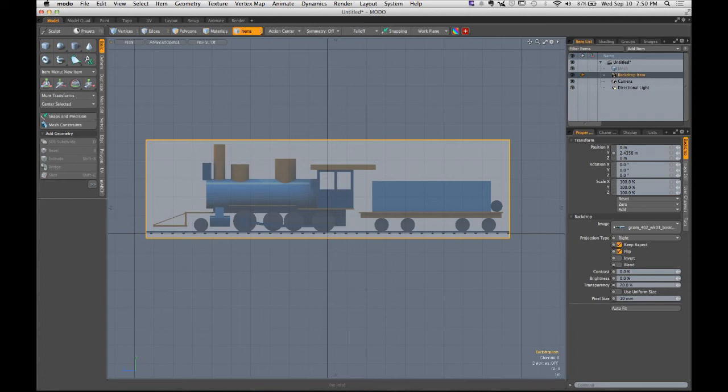The only way to do that would be to change your projection type from left to right. How do I do that? Go back into your double arrows. See how your projection type's from left. Now jump over into your right. Boom. There it is. Thanks.